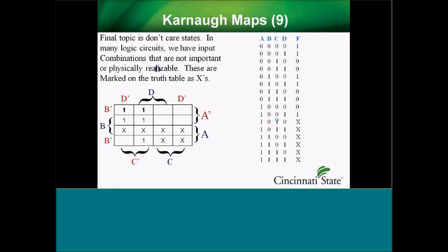I've got one here. So I basically just took a function here and I said, okay, I'm going to put a bunch of, the don't care states are marked as X's. Okay, this example here is a specific type of don't care state. It has to do with BCD numbers. Basically if you're doing things BCD, it only goes 0 through 9 and everything above it is don't care. So I tell them that don't care is literally what it says. You put it on the map and you don't care if that X is a 0 or a 1.